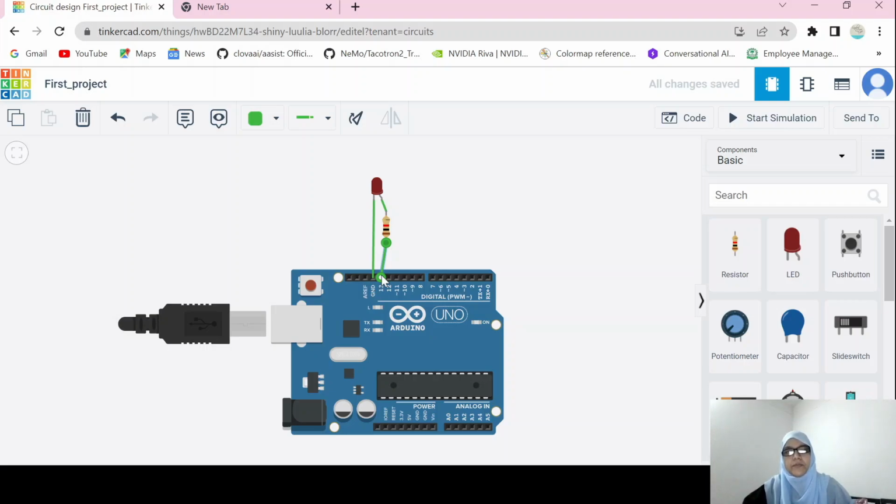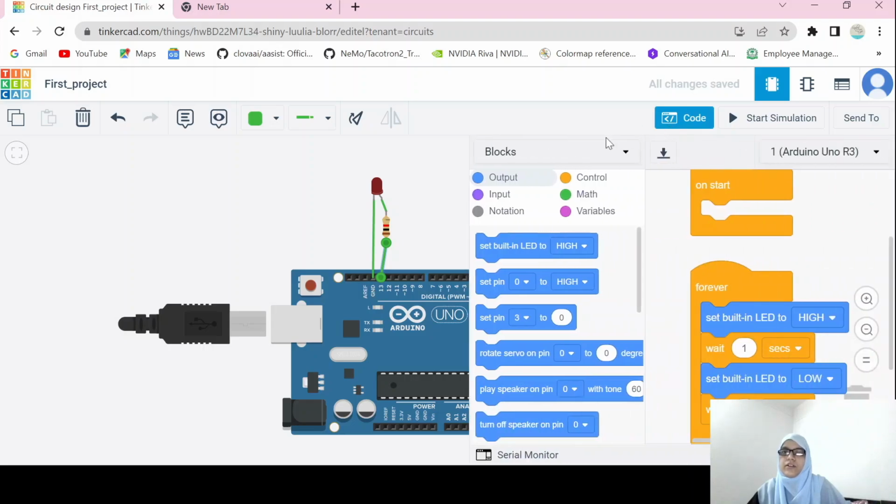This is the built-in pin, whose status you can see here at L when you turn on the board. This is also for debugging, to check whether the power supply is going into your board or not. And this wire is grounded to complete the circuit, as this resistor is the current limiter, so that our LED will work properly. So let's see how the code goes on.